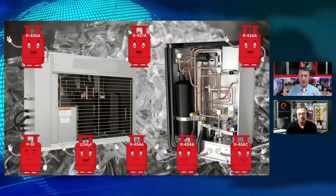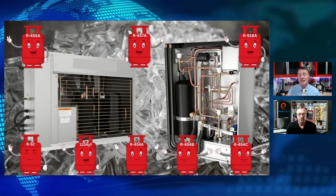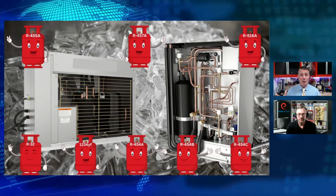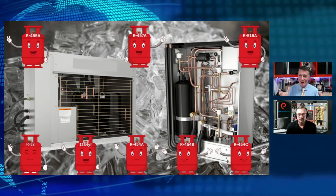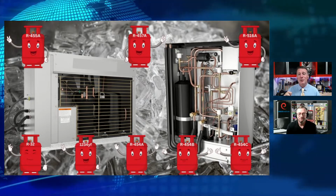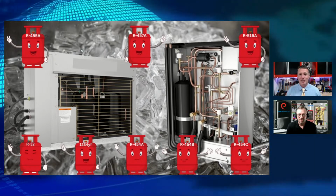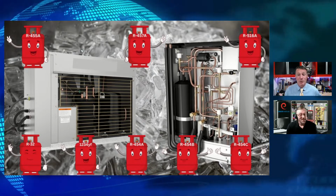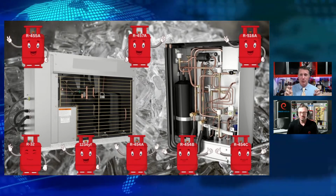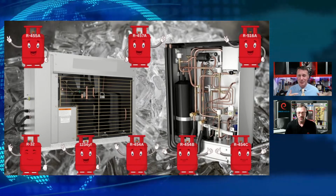We're going to talk about R32 in residential and light commercial air conditioning systems, in window units, PTAC units. We'll dive into that a little bit later. It is a very good refrigerant for those of you that are not aware. R410A, that refrigerant that we're so comfortable with in air conditioning applications, half of it is R32 already. If we would have been as prepared for mildly flammable refrigerants 20 years ago as we are today, we would have gone with R32 instead of R410A.